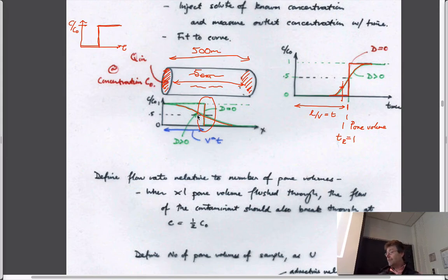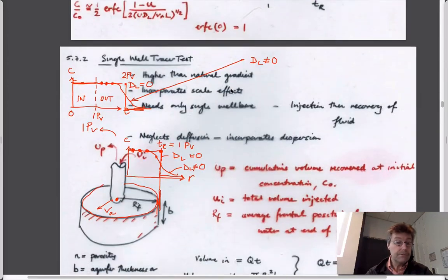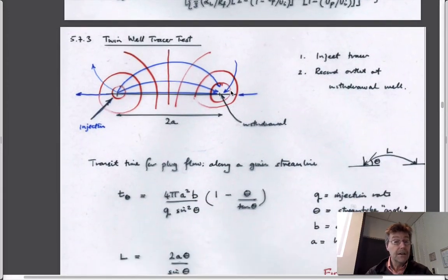Actually, some people have done that. Some people have worked in, perhaps we'll talk about in site investigation, digging a trench upstream, a trench downstream, maybe 5 centimeters apart, increasing the gradient slightly upstream, decreasing it downstream, putting tracer in the big trench upstream and allowing it to flow from one side to the other, and looking at the residence time distribution as it arrives downstream. But the other way to do this, if you're not doing that, say if you wanted to be at 20 meters depth or 50 meters depth or 100 meters depth or a kilometer's depth, is to do it by using wells.